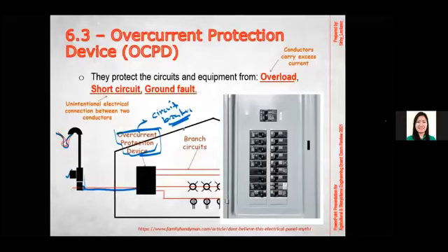Okay, and if we talk about the final circuit breakers, because it's also possible to have another panels right here for, let's say, electric motor loads and things like that. But if you're referring to the final overcurrent protection device, from this device to this one, this is what we call, if I'm not mistaken, feeders, or main feeders, or sub feeders if there are subs.